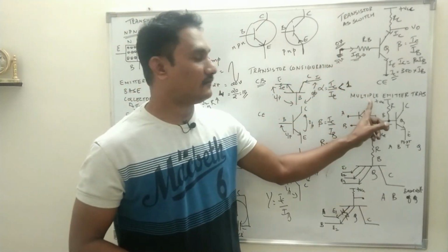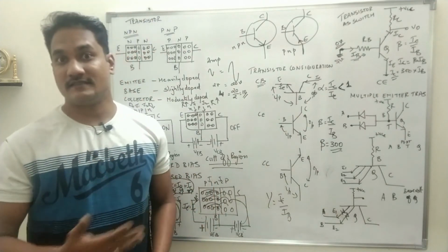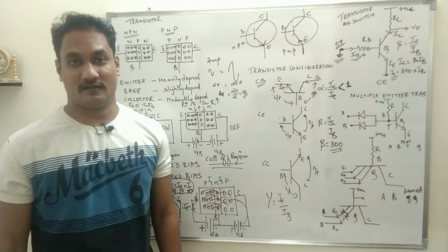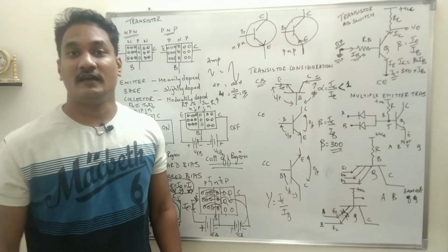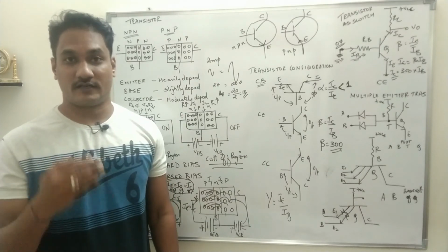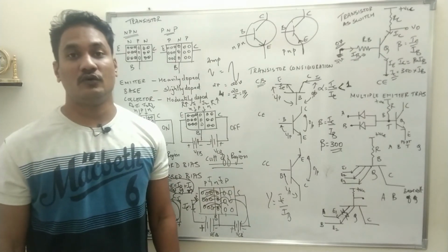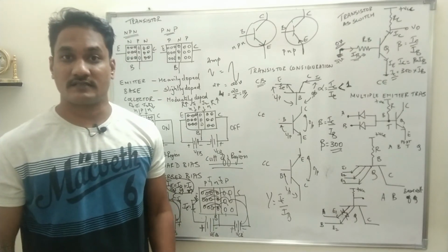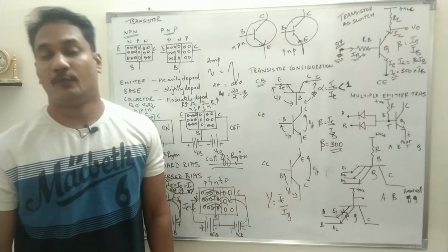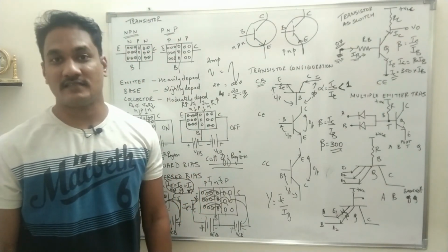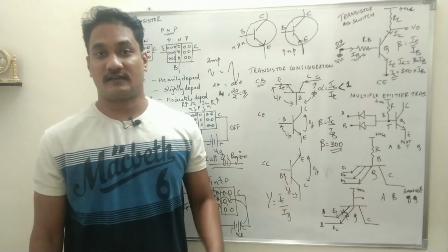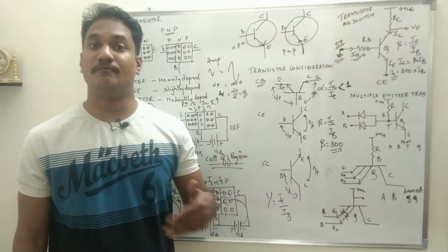Next, we are trying to understand chapter number 3, which we have skipped. In that we will try to understand two types of logic families, TTL and CMOS. For TTL, the transistor which we are going to use is the BJT, bipolar junction transistor, because current conduction is due to both charge carriers, electrons as well as holes. For TTL logic, the transistor which we use has multiple emitters.